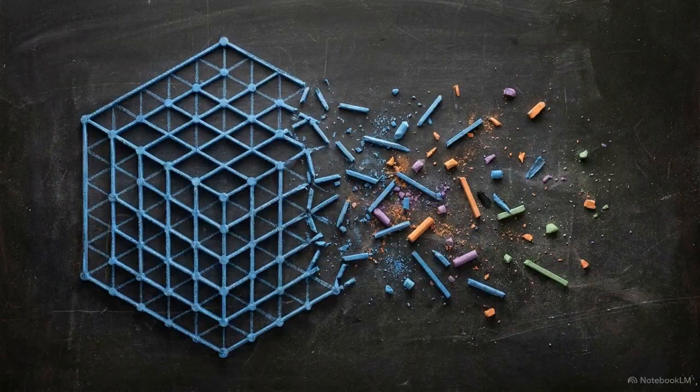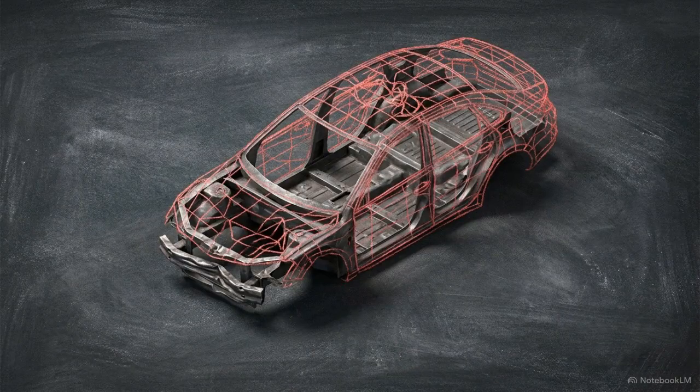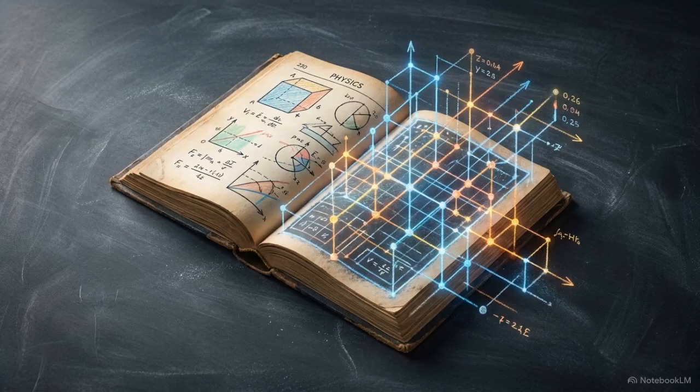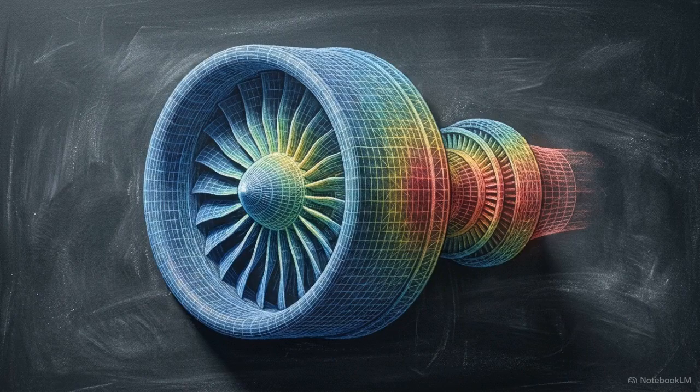There are boundaries to this approach. If you're handling highly advanced, highly nonlinear, specialized physics problems, this simplified, pragmatic foundation may expose some gaps requiring further mathematical rigor. However, for standard finite element analysis and for the curriculum covered in our upcoming engineering models, this foundation is entirely robust. Translating abstract variational physics into discrete mass and stiffness matrices takes the concept of energy minimization out of the textbook. It equips engineers with the exact operational tools required to model and solve complex structural realities in software.